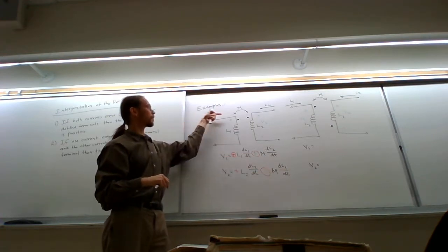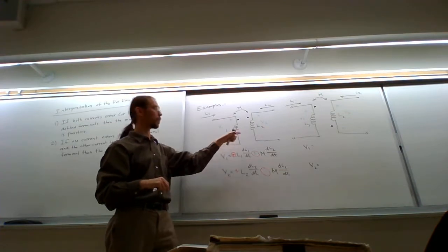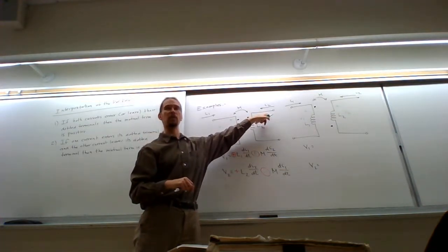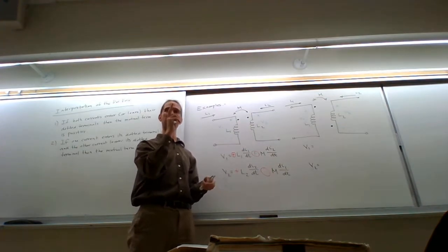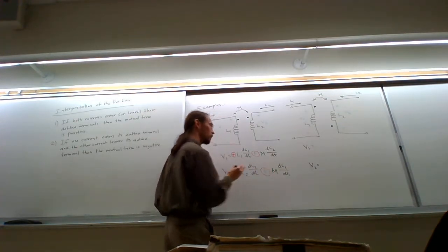Over here, this current is entering its dotted terminal because it hits the dotted terminal before going through the inductor. Is this current entering or leaving its dotted terminal? It's entering. Both of them are entering. Therefore, the mutual term here is positive.